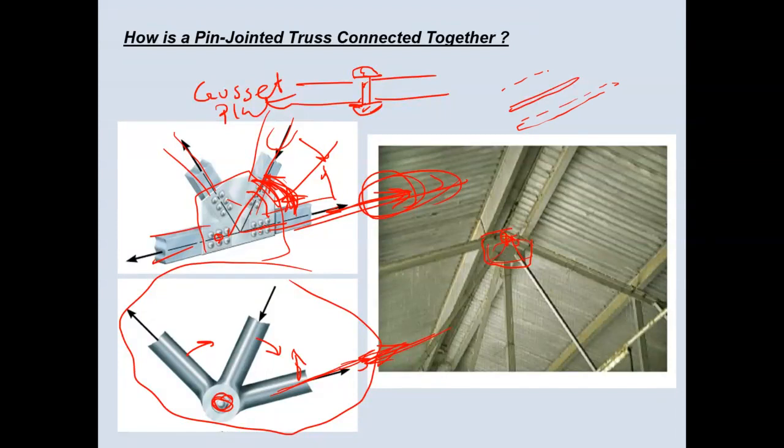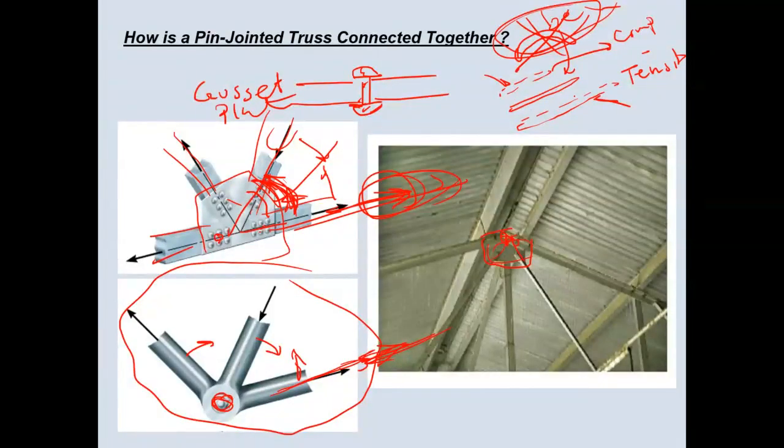If that becomes shorter, it becomes shorter like that, but it never bends. When it bends, that is the deformed structure of this one. So in a truss structure, you never get this. You either get the member to become shorter or longer. So that is when your member is under tensile load, and this is when your member is under compressive load. That is bending. This is bending. So we assume that bending does not happen in the truss structure.